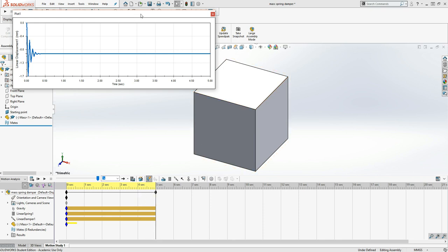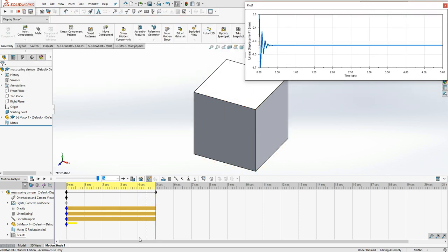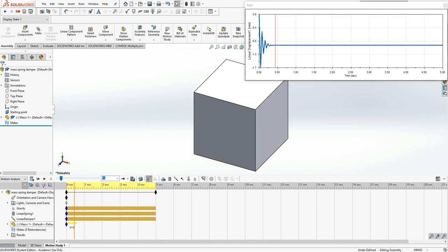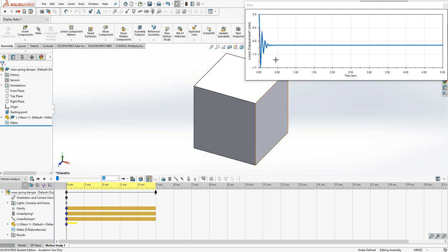So, let's bring this over and then drag the time bar back. It means really all we need to run this for is 1 or 0.5 of a second. I think we just go with 1 second. It still gives us that freedom for a little bit of configuration and changes. At the top you have a black key properties bar. This is set to a default of 5 seconds every single time. But if I left click, keep my finger on it and then drag it, I can go back to 1 second.